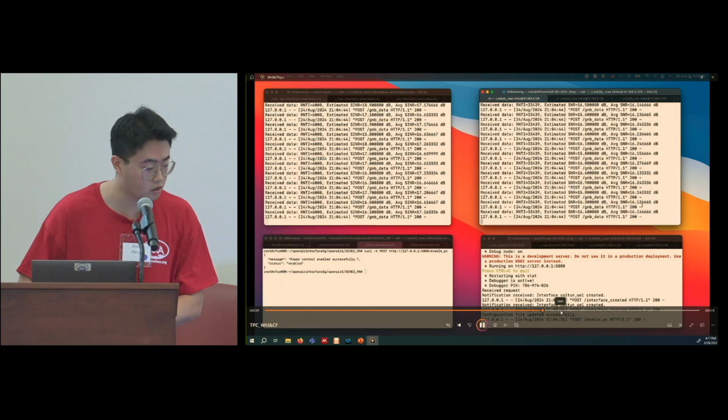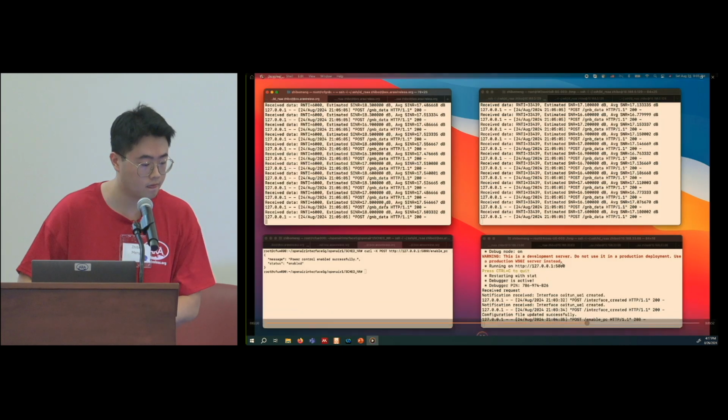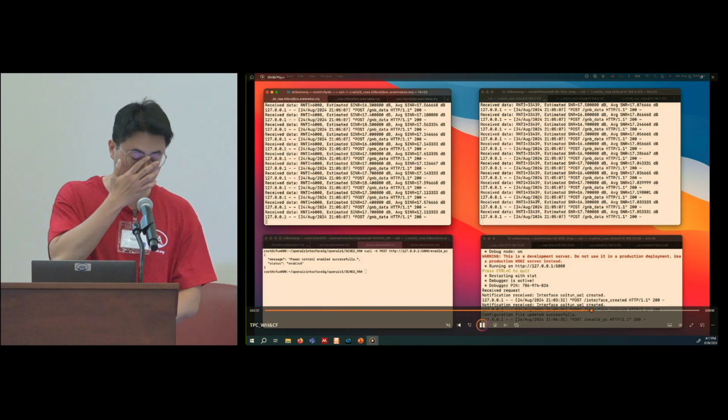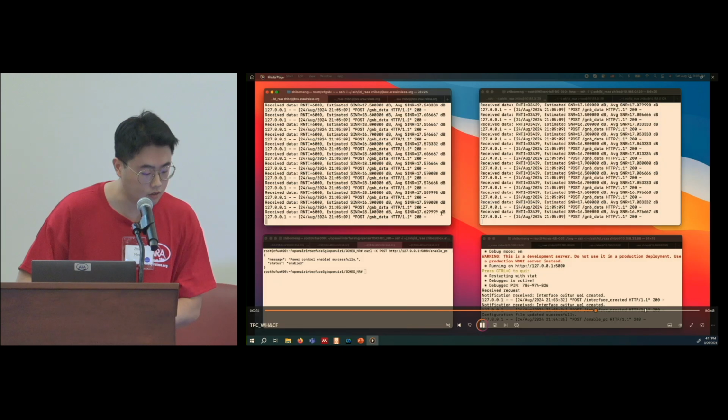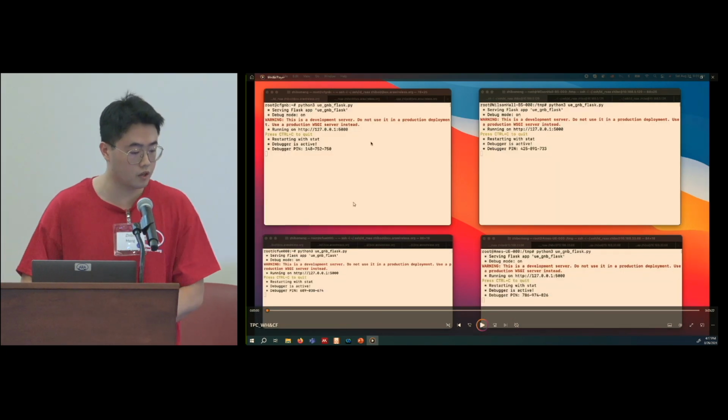And then I just increase the SNR threshold a little bit. Right now the threshold is 16. And I think finally we can increase it to about 19. Oh, I think 18 may be the final threshold. So that's it for the interference.